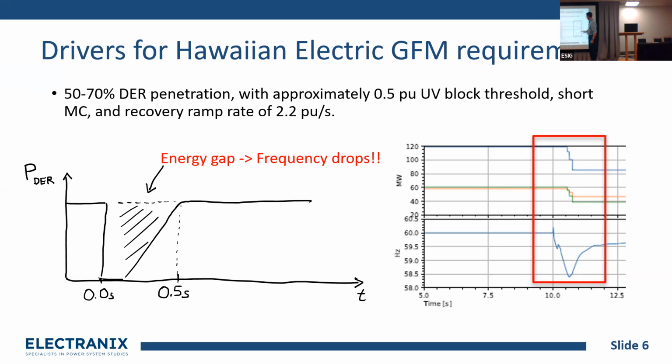So now, what's going to happen because of this energy gap? The top plot you can see here is not megawatts of generation, but megawatts of load. Okay, what the Hawaiians are going to have to do to preserve that system is to start dumping load. If they get frequency that drops this low, their under frequency load shedding is going to start kicking in. Okay, so we're going to lose a whole bunch of load. So not good.